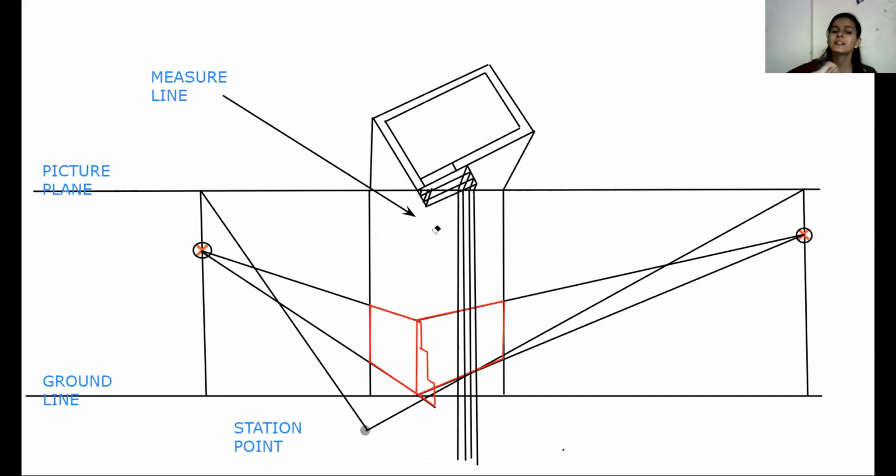So your perspective view from the left projections will look like this. Now you need to consider 7 points on these steps. This 1, 2, 3, 4, 5, 6, and 7. Okay. Now firstly, to draw the first section of the steps, we have connected it to the left side vanishing point. Now consider these 7 green tick mark points and connect them to the right vanishing point. So you will get 7 lines. First line is already drawn.